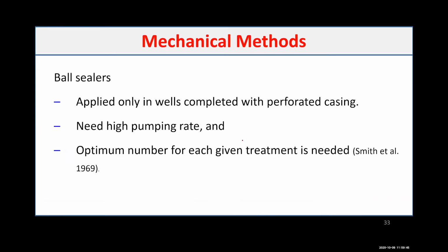Again, we have ball sealers, which are still part of the mechanical methods. They work only if you have a perforated well. You need to have a perforated casing and cemented. Also, it needs a high pumping rate. If you are pumping at a low rate, it will not work. And designing how many balls you need to run is a little bit critical, and not all the time is it designed right. You may actually plug a formation that you actually need to treat. So it's still a little bit tough to deal with.